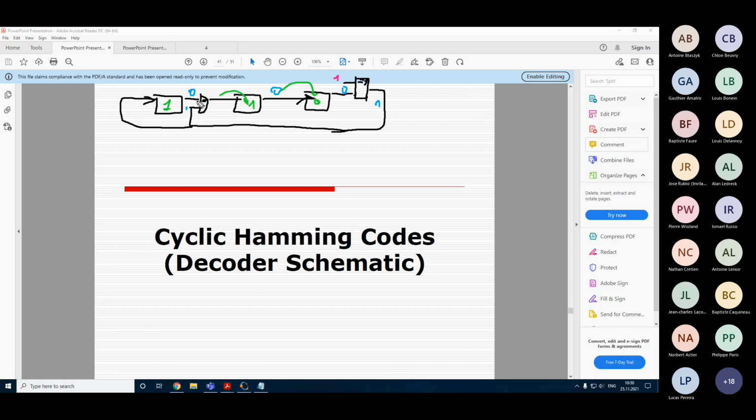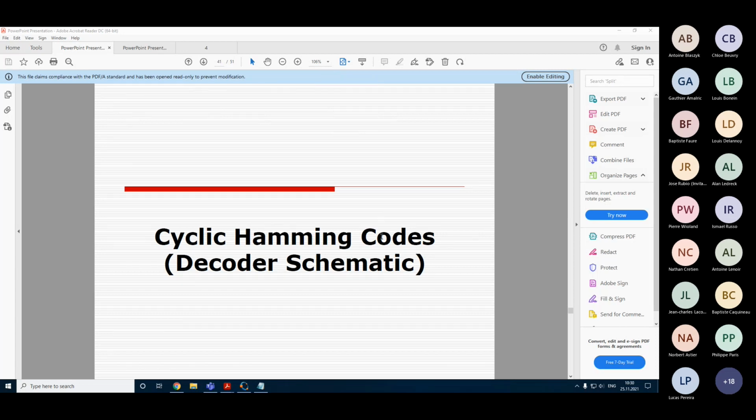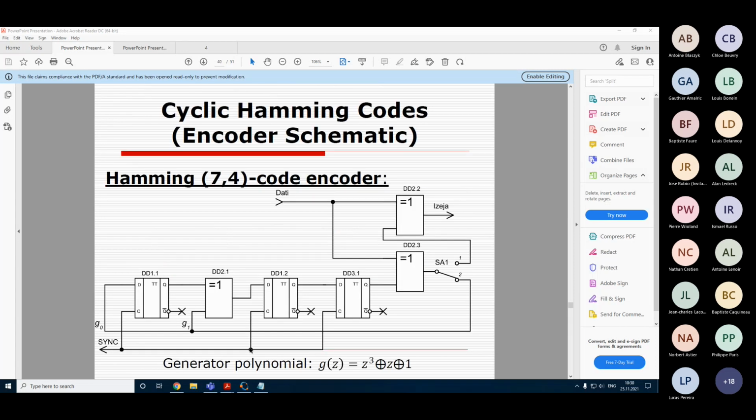Next symbol comes here, for example 0, and the whole process is repeated. Everything is sent to the outputs. This XOR generates feedback, and this feedback is recorded here, and here the feedback is recorded with the output of the previous state of this flip-flop. So this process continues for 4 intervals, and that gives us the remainder.